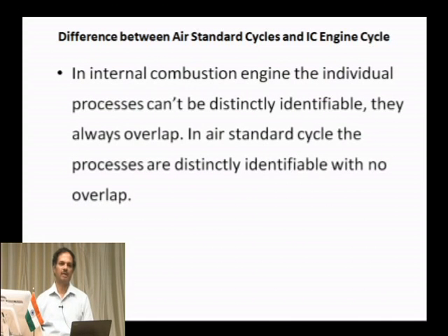And one more is, in the internal combustion engine, the individual processes can't be distinctly identified. They always overlap. One process will overlap with another, whereas in the air standard cycle, the processes are distinctly identifiable without any overlap. This is another difference between these two.